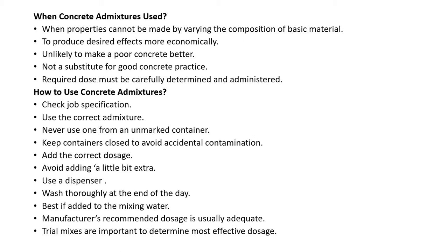It is best if added to the mixing water. The manufacturer's recommended dosage is usually adequate. Trial mixes are important to determine the most effective dosage.